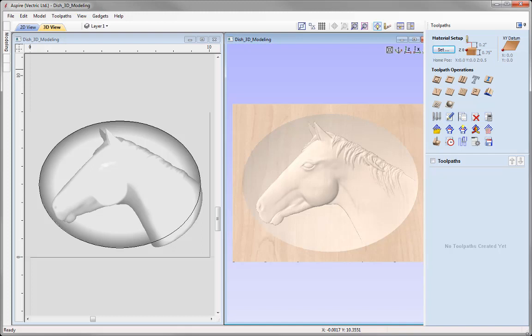In this case, with a dish, your first pass is almost going to be on the surface of your material, and so it's barely going to be taking any material, and after that it's just going to be running back and forth, only shaving off the distance of the step over. And so the force of the tool is much less than you get with normal 3D toolpaths. So you must make sure that this is safe for your setup, and in this case we're just going to assume that it's okay for our example.